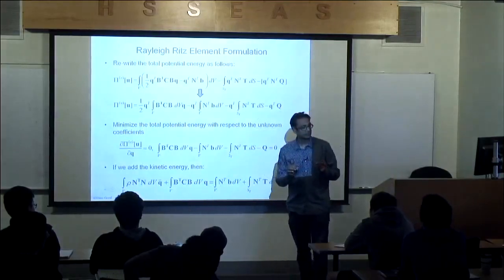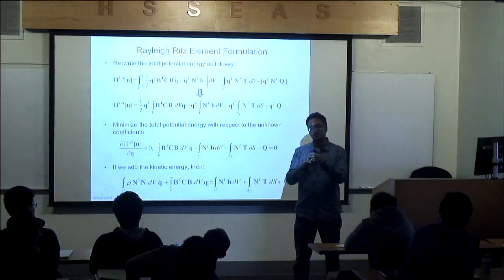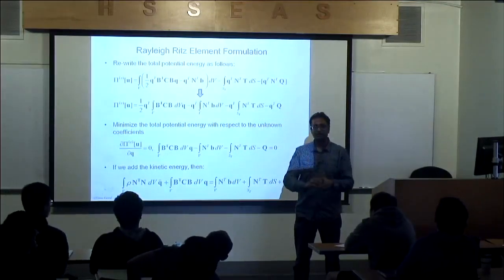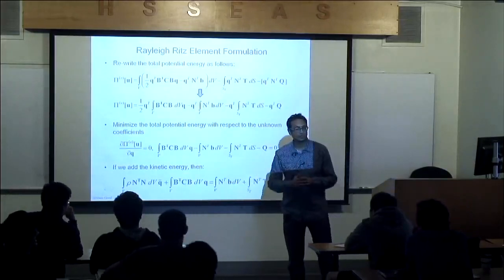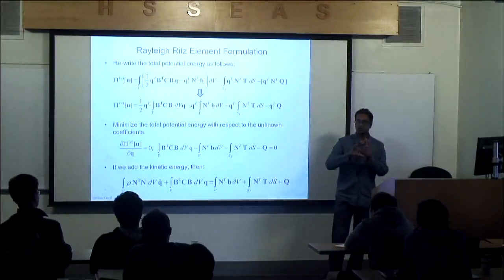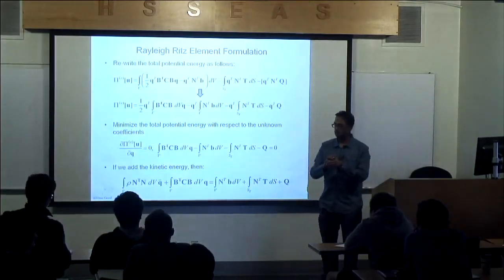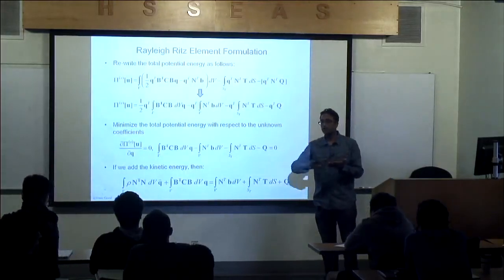Well, let's try to decouple the element geometry, map that out to a cube. It would be really nice if everything looked like a cube. If I can make it look like a cube, then I'll have even more success in trying to solve these equations. These I can integrate over that cube more easily. I can also, the shape functions will be the same for all of them, and so forth.